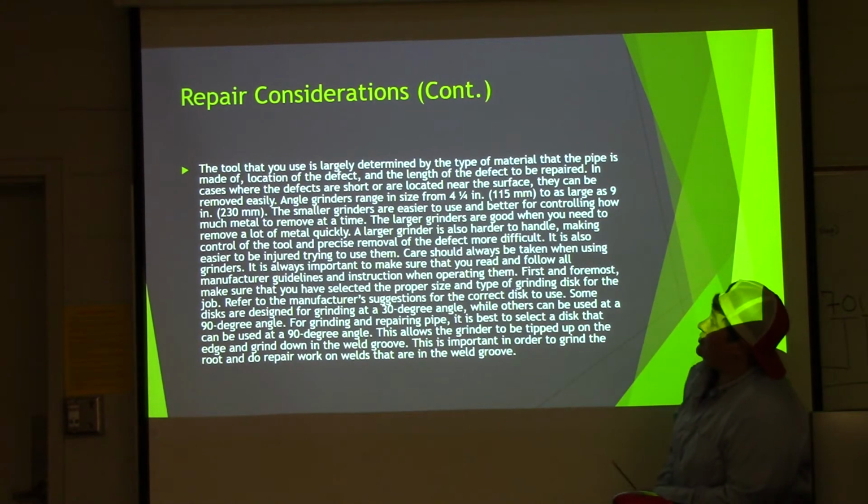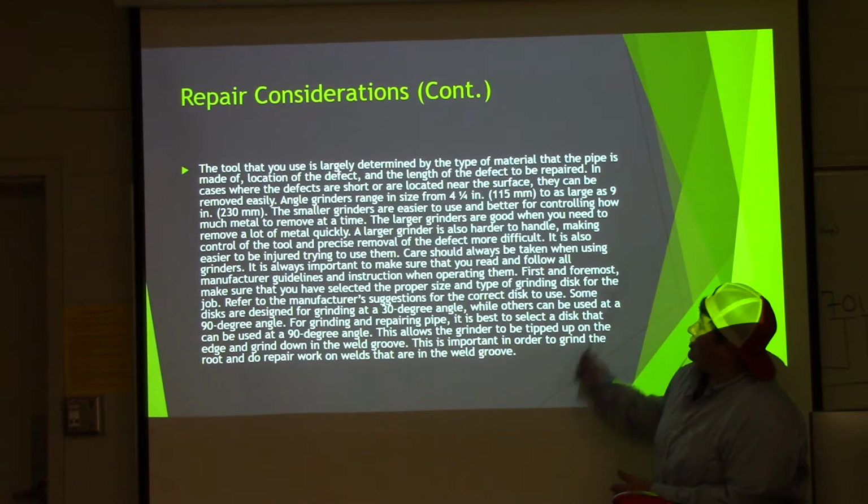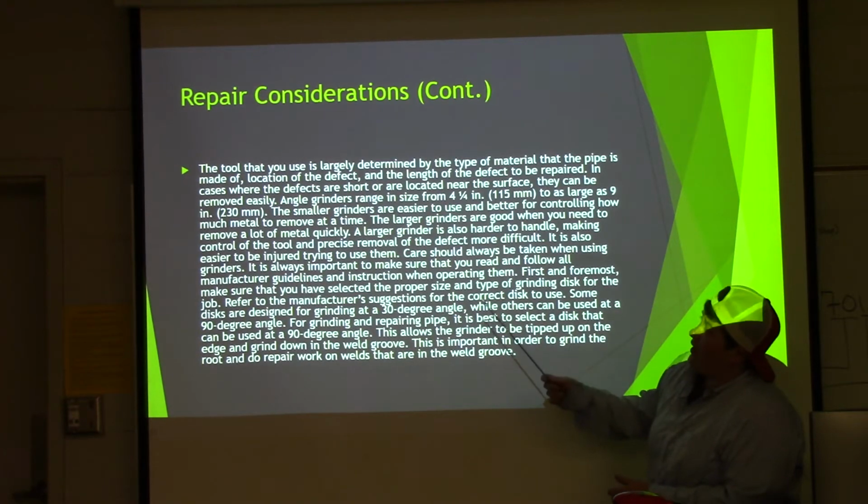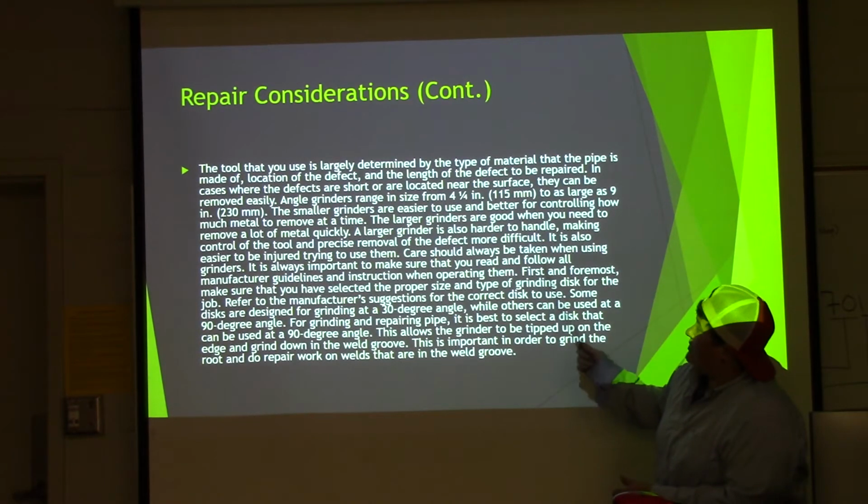The smaller grinders are easier to use and better for controlling how much metal to remove at a time. The larger grinders are good when you need to remove a lot of metal quickly. A larger grinder is also harder to handle, making control of the tool and precise removal of the defect more difficult.